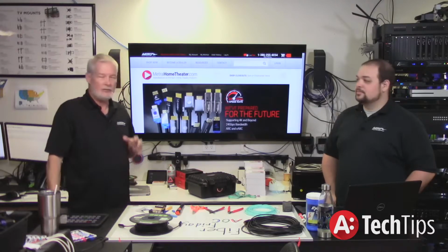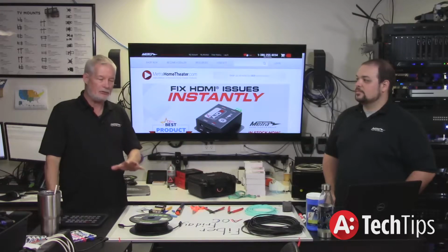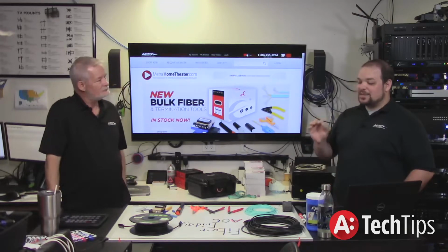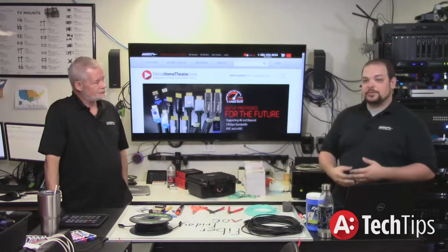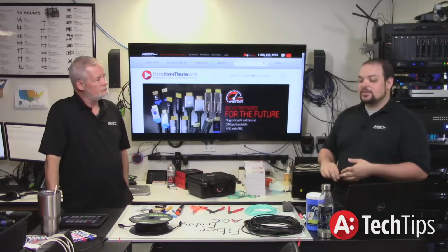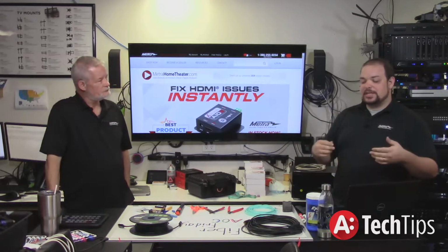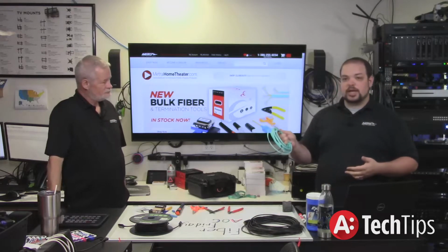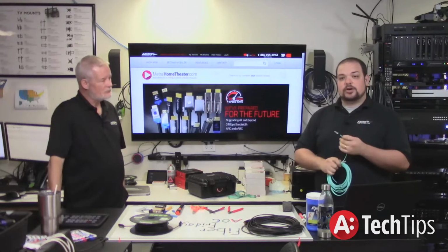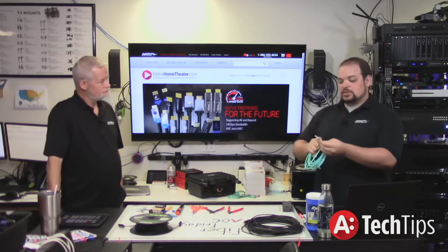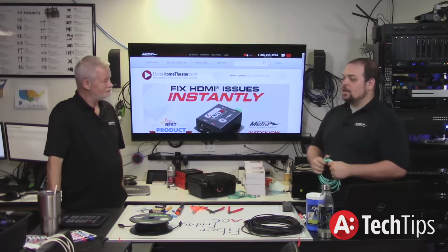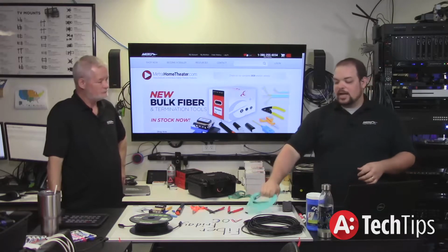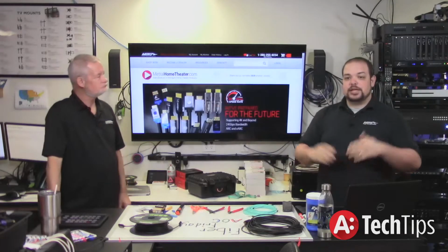That's what we're here to talk about, because there's a lot you can do with this today and a lot of different variances in fiber today. Specifically, the type of fiber inside our AOC cables, or our HDMI AOC, is OM3 fiber. The nice thing is it's multi-mode, it's OM3, so we sell OM3 bulk fiber multi-mode cable. So what you can do simply is take our terminations for our fiber, lop off the ends of the HDMI cable, and use any of those 4 fiber strands inside of there. And they are color-coded? Yeah, they are. Just attach that termination to it, and now you've got a fiber cable.